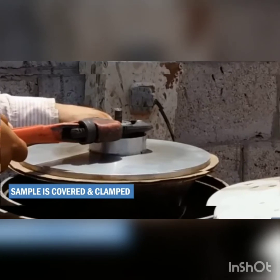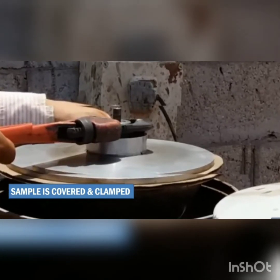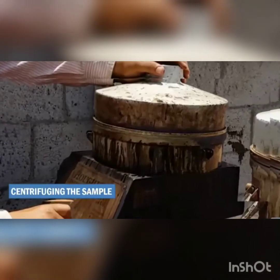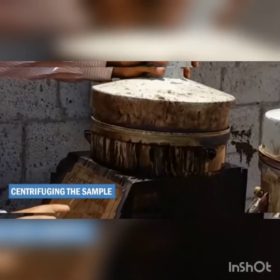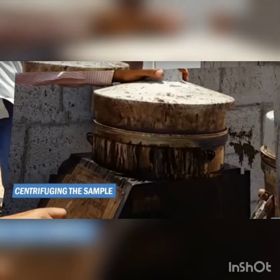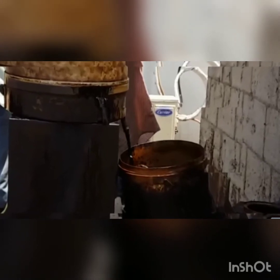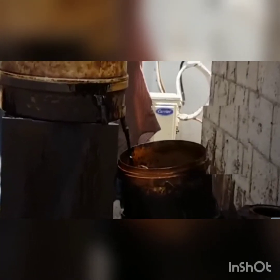The bowl is then covered with a steel cover and is clamped tightly before placing in the apparatus. A beaker or a clean container is placed underneath the drain outlet of the centrifuge apparatus for collection of the extract mixture of solvent and bitumen. The next step is to centrifuge the apparatus. The bowl is placed in the apparatus and the machine is started to revolve. The speed is gradually increased till a maximum speed of 3600 revolutions per minute is attained.